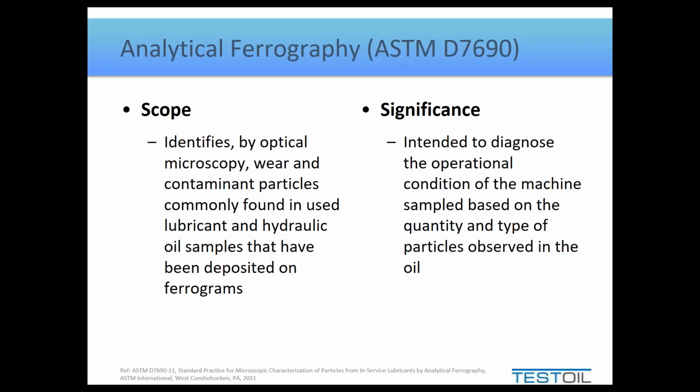Now the significance of this test is if we understand the morphology of the particles, we understand based on its shape and size what wear mechanism created it and how severe that wear mechanism is, we have a pretty good idea on how that system is operating and how severely it may be wearing.